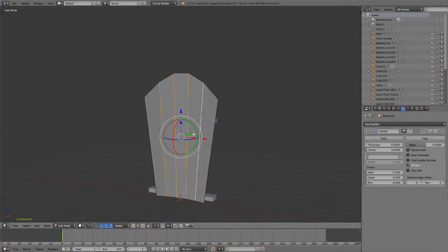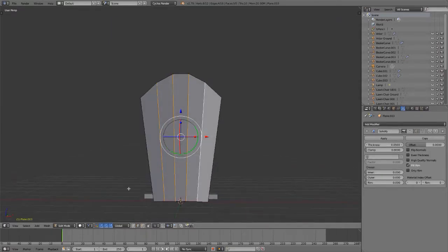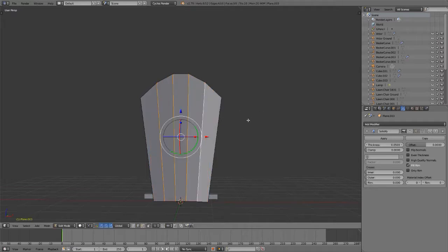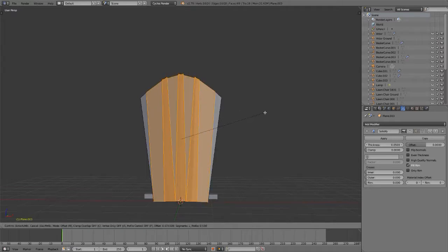All right, so let's look at this thing. Select those on the inside. And Control B, let's bevel them so that they are eyeballed a third. See, they won't fan out very well. The benefit of doing it this way is that they don't fan out equally. As you can see, they overlap and crash, but the distance between the slats will remain a constant, allowing the slats to appear that they were manufactured wider at the edges.